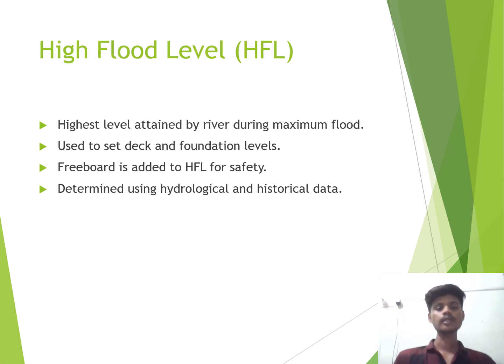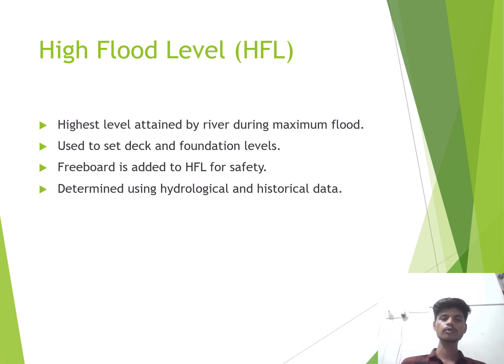High flood level (HFL). HFL is the high flood level attained by the river during the maximum flood. It is the average of many years. It is the highest level attained by the river during the maximum flood. It is used to set the deck and foundation level. The deck must be above the HFL.